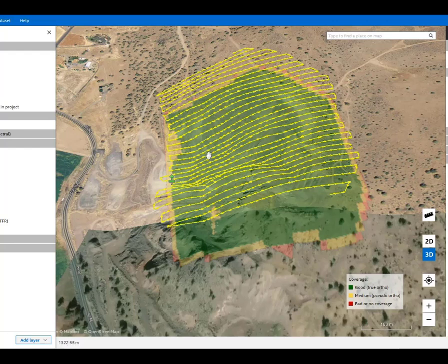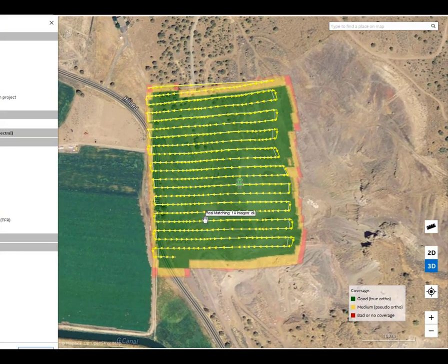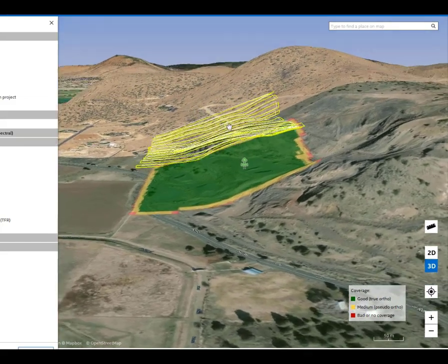And of course, then you're kind of just limited by line of sight, the having to keep the drone within line of sight. So this was the quarry area. This was what, 884 images, and then we had a separate flight down over the gravel stockpiles, and then both flights, all the data was put into Pix4D and processed simultaneously. This is the flight over the gravel stockpiles, and you can see again, it's the terrain following flight.